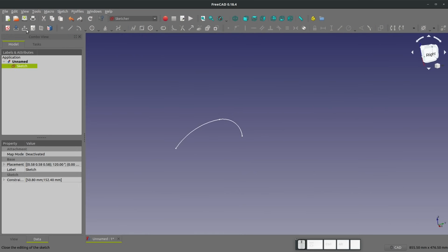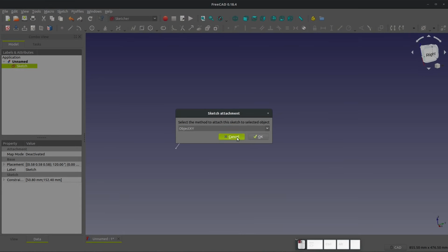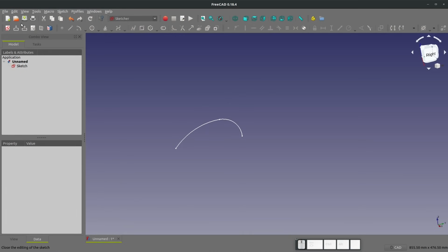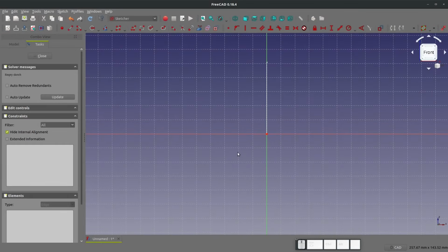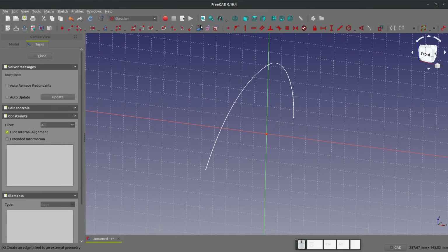From here, let's switch onto another sketch, and actually let's have nothing highlighted when we go onto the sketch. And we're going to say our YZ, or front plane. The first thing I'll do is import the tangent point between my two arcs. And that'll be a good little connector here for another arc. Alright, so I'm going to choose the body of my arc.